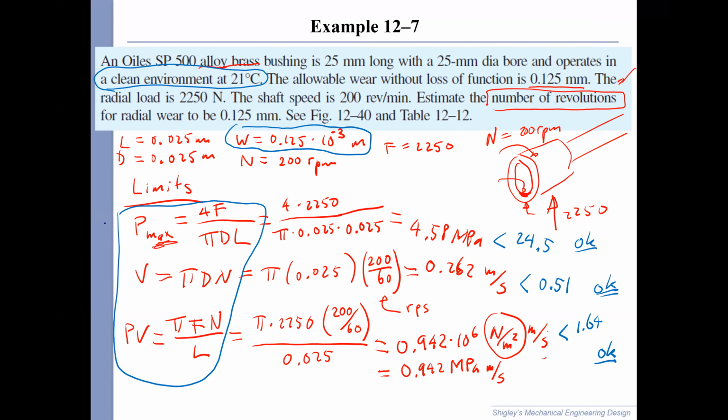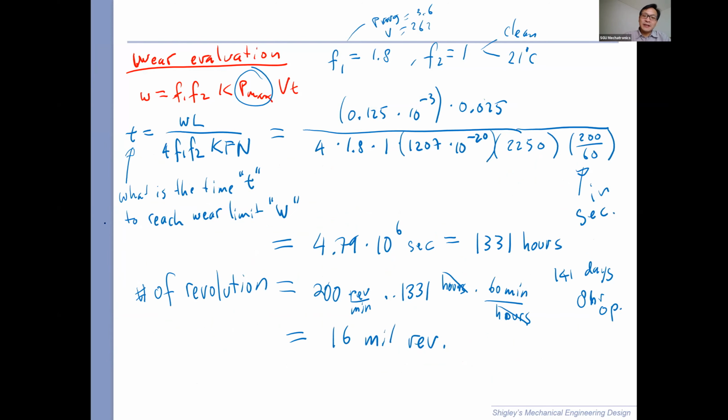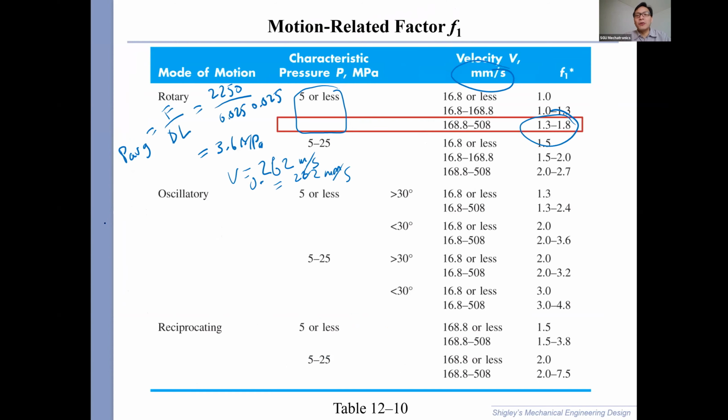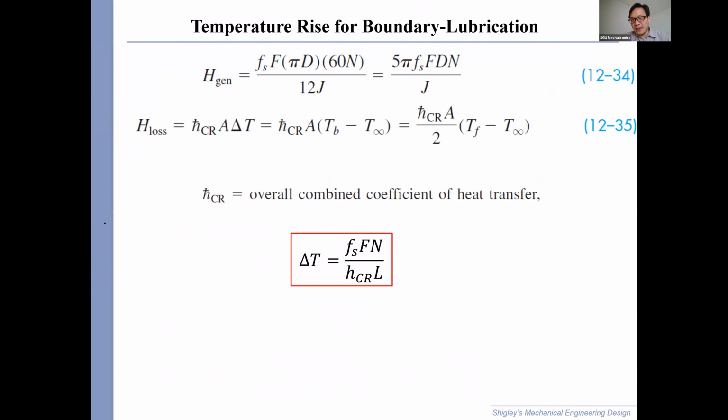Yeah, it's not as straightforward as it seems. Because if D is small, we can get good V, but the pressure P is large. If D is too large, V will max out. So, unfortunately, we have to do some iteration, or in other words, trial and error.